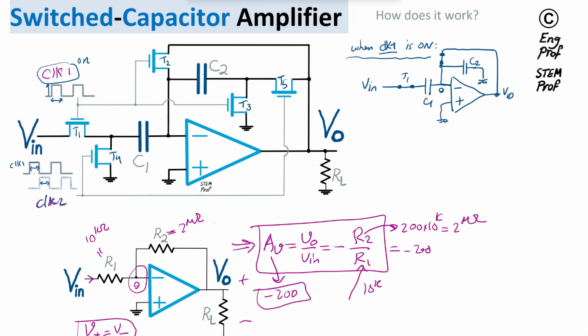Now, what happens is the circuit tries to naturally charge C1, and the output of the op amp effectively is grounded, so it is 0 volt during this time. We don't care, that's not the output we're going to monitor. So as if the output at this time is a don't care.